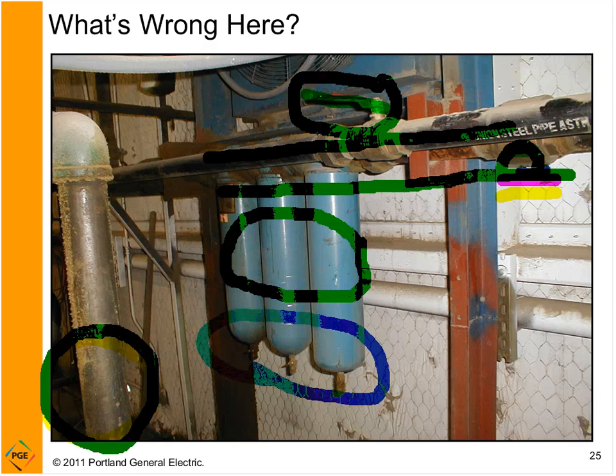Up here you see the fan with the cooling coils. It's basically a radiator with cooling coils in there. Those can also clog up with particulate matter, and then they don't do a very good job cleaning. So I see some opportunities here. Replace that filter, close the valve, and do a good job at cleaning the air.